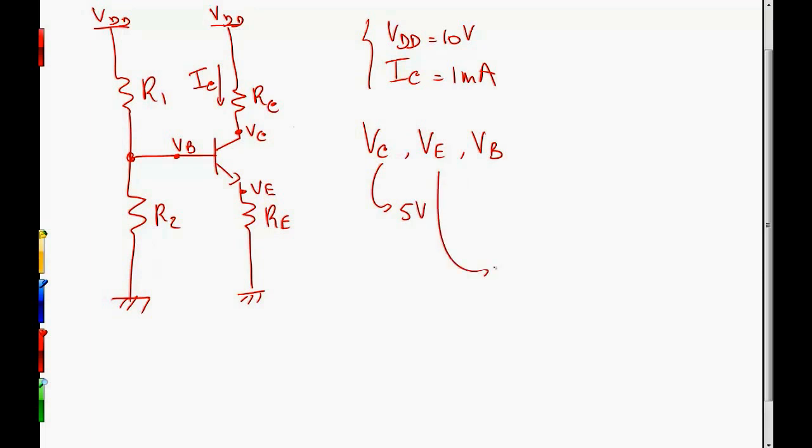Now the emitter voltage. Now if the emitter voltage is chosen to be very low or even zero, the emitter resistor will not play a significant role in the biasing. And so the biasing will be very dependent on the transistor, which is a bad thing, as beta, the forward current gain, can vary a lot. If it's high, let's say in this case 3 to 4 volts, then the transistor will be close to saturation, which limits the voltage swing at the input and at the output.